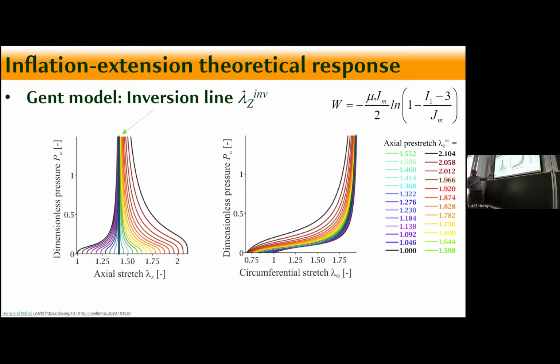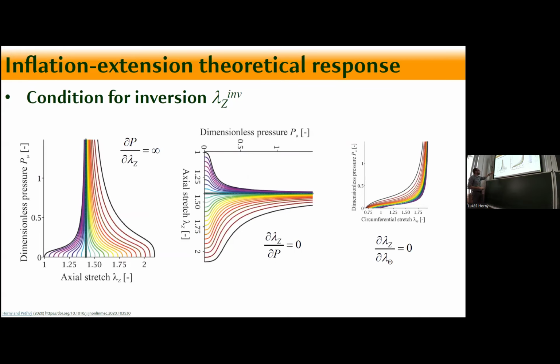We see how we can derive it, and this is the idea with this picture. How we can derive the derivative of the pressure. When we take the inversion relation, we see that we can think about the derivative of the axial stretch with respect to pressure, and then we will make an interchange between pressure and circumferential deformation. This is for the incompressible material when we already substituted or eliminated dependence on the third, radial stretch ratio and consider the problem as only a two-dimensional strain energy density and do not take into account shear strains.